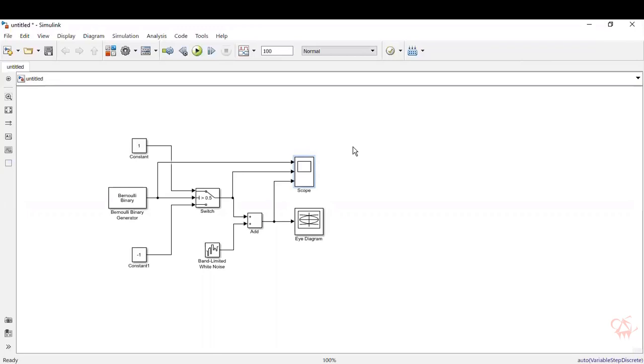For example, let us say here for each second there was one sample that was spanning the entire second. Here we'll make it for 0.5 seconds. It will be at 1. Then for 0.5 seconds it will be at 0. Then another 0.5 seconds, for example, for a 0, it will be at -1. Another 0.5 seconds, it will return back to 0. So this is how the RZ signal is generated.